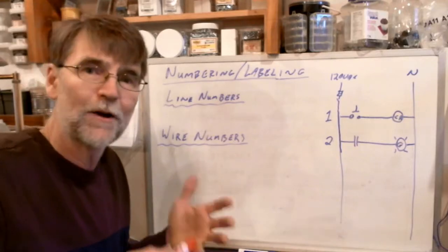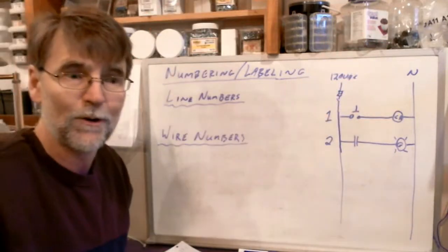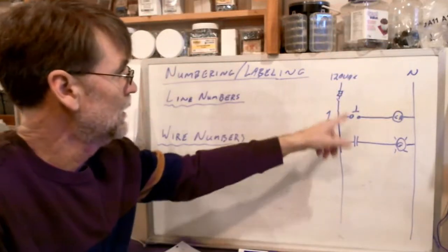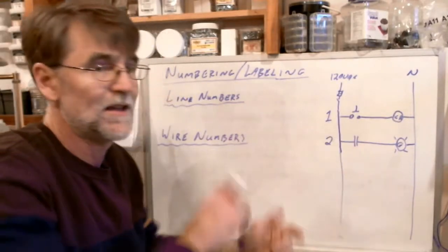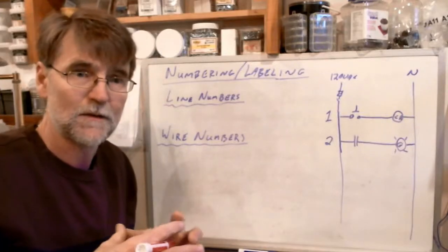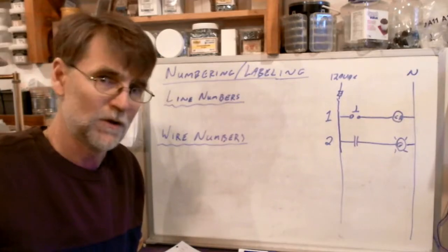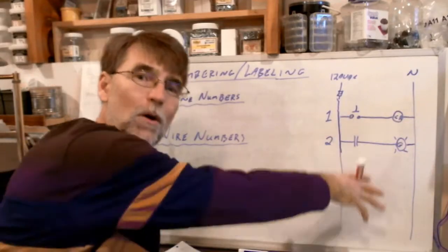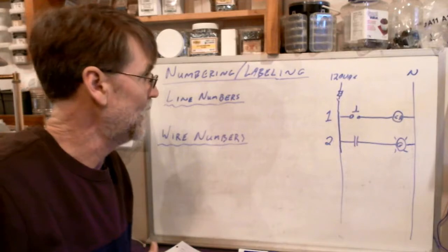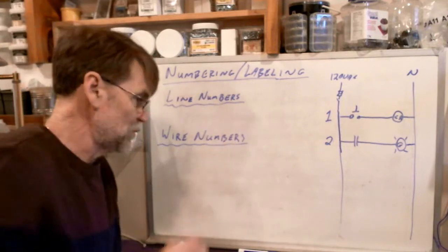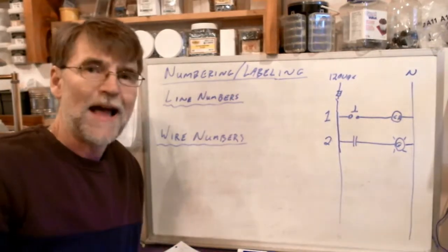So if we actually number the wires, these are all single conductor wires that we've got spread around our lab station, and while these two items might be together in the same place, some of these things may be a very long way away, especially in a real world application where one wire goes from the control console in the control room across the plant to the motor starter at the motor. How do you identify what wire is what? We do that by numbering the wires. We will actually attach numbers right onto the wires. So how do we do this?